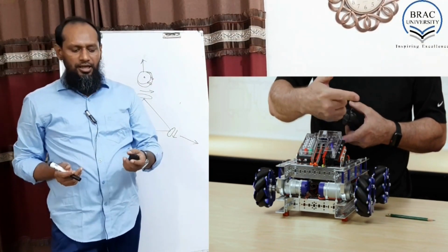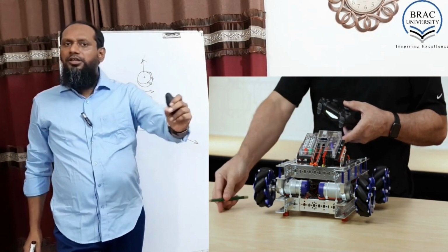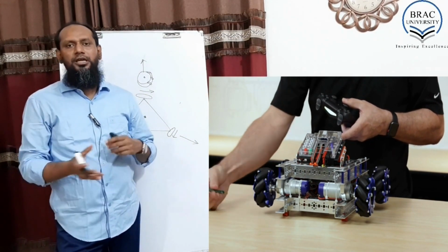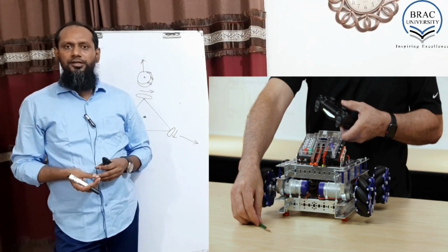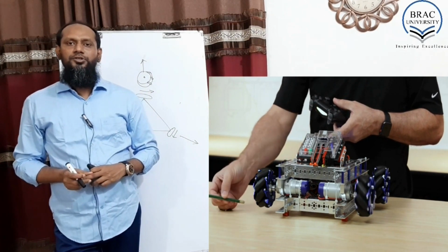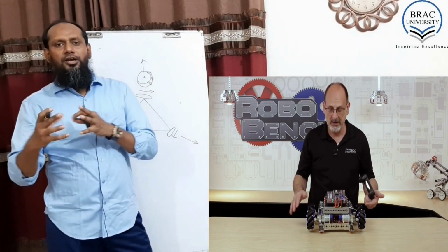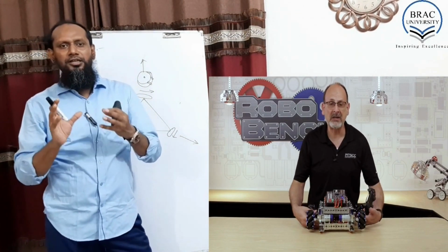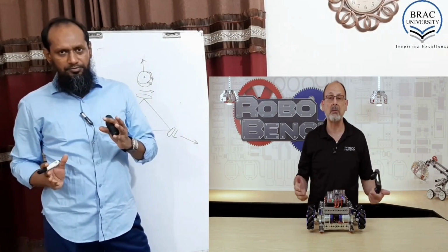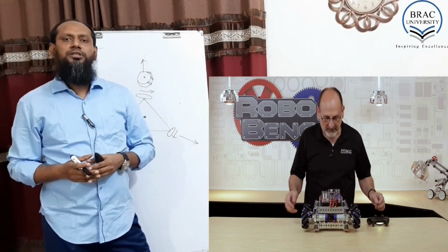Very, very interesting. But the problem is, since the outer units become stuck with some dust and some materials, it cannot be used on outdoor surfaces. But for indoor, this is a very, very interesting wheel. In a number of competitions where you need to move your robot in any direction, you have to change the direction very fast. To change the direction very fast, these kinds of wheels, omni wheels, can be used.